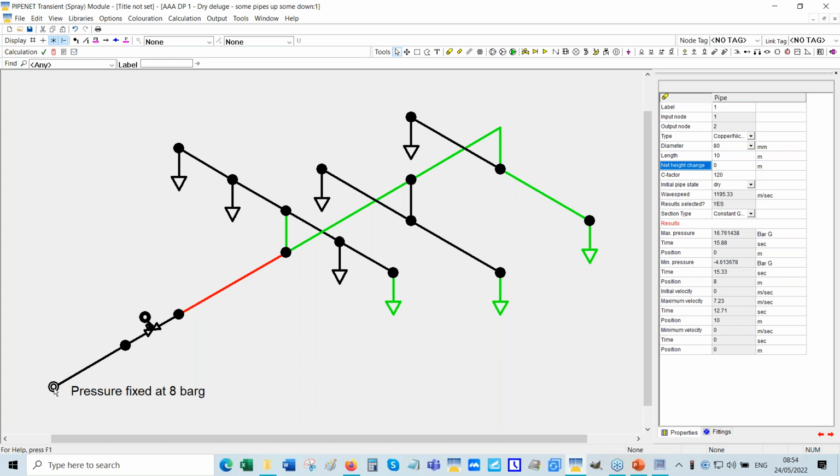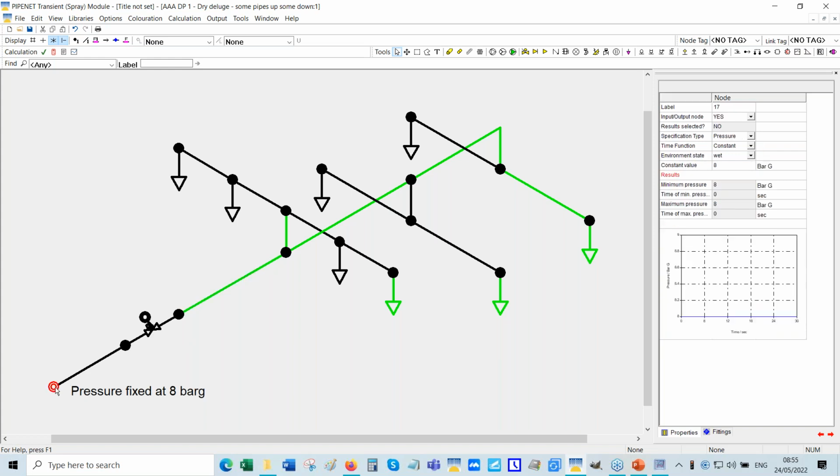You can tap from the fire watering main at the same position, but place the deluge valve at a high point in the system, or alternatively, you can connect to the ring main at a higher point. In either case, it is quite a substantial modification, which was unfortunate.